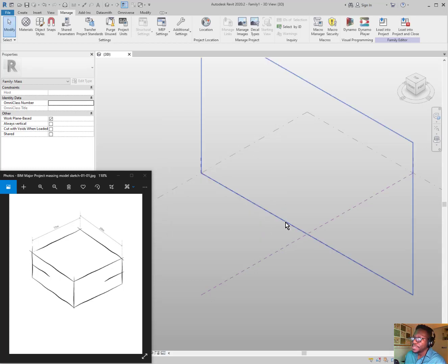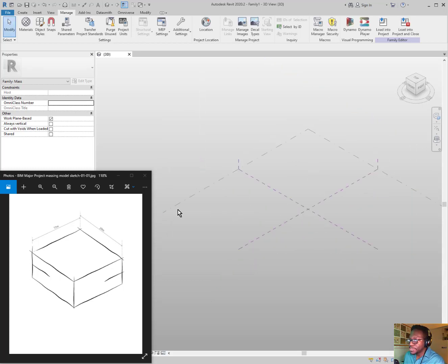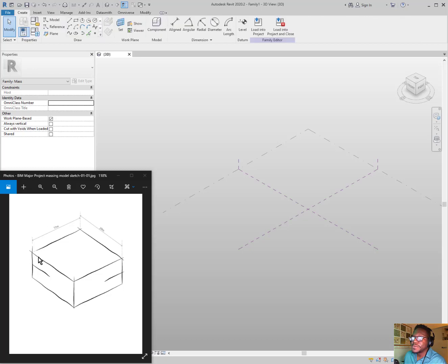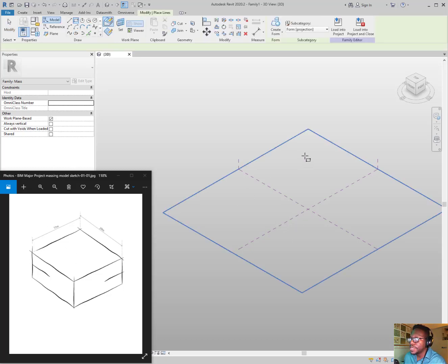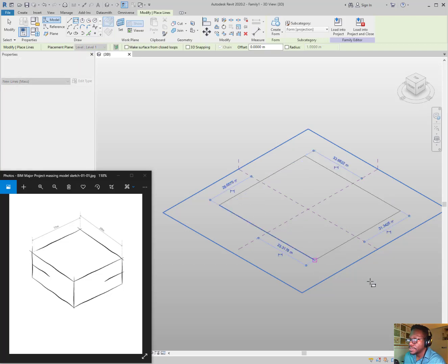All right, now you'll notice this space that is here is really meant for us to begin the modeling process. This point here is actually the center of our model, and it's a real good idea to just have your model within this space. All right, so we're going to first draw that box. So we're just going to use the rectangle tool and put a box there.